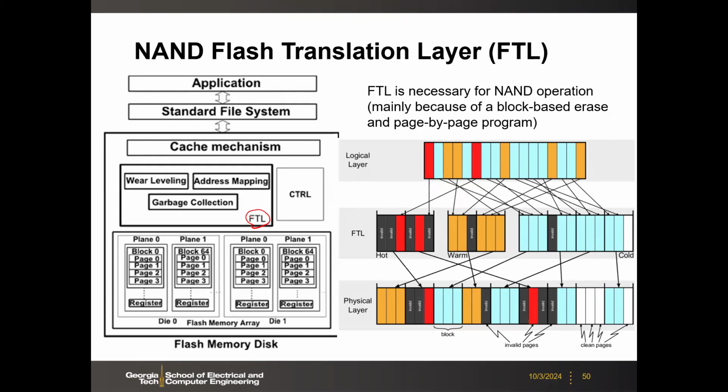What is important is that in the logical layer, you have many pages of data, right? Each page is, let's say, 16 kilobytes. In the logical space, they may be continuous from your software point of view. For example, you have one image, let's say 1 megabyte of pixel values, and you save that to your SSD. From the software point of view, they're continuous, the same image. But when you store that to the flash, maybe they are discontinuous. They are stored in different locations, okay?